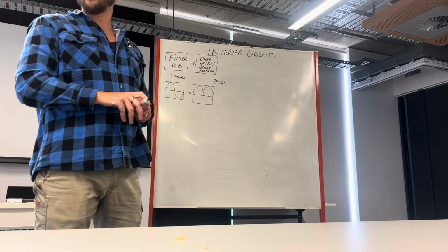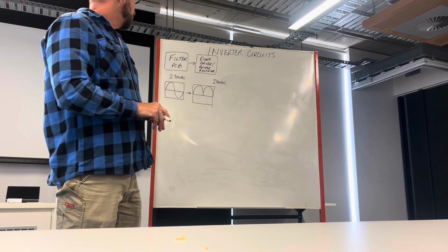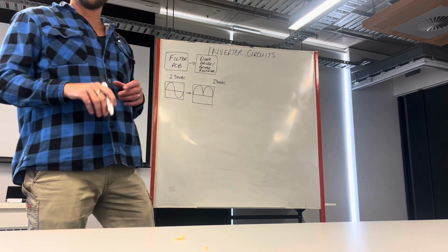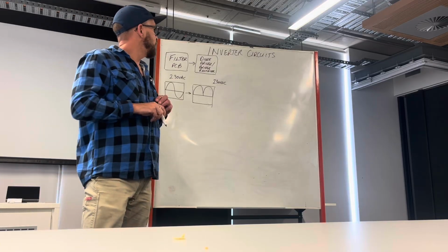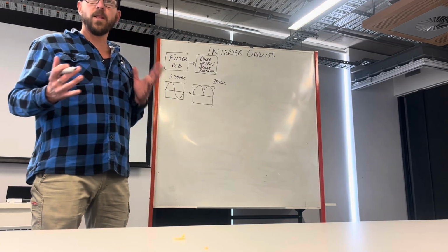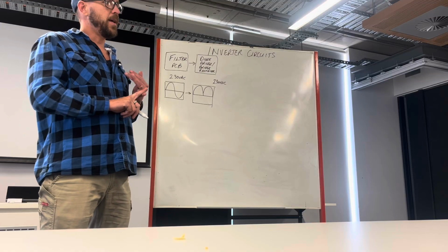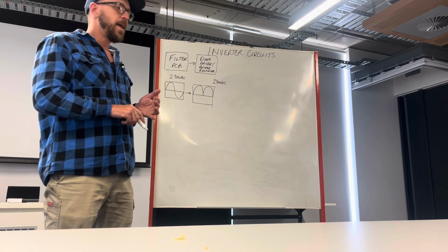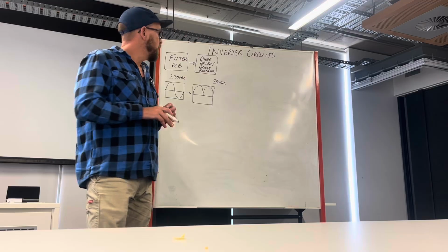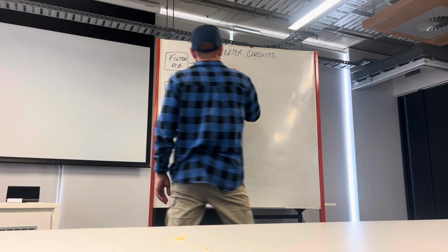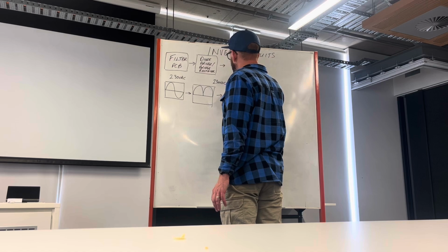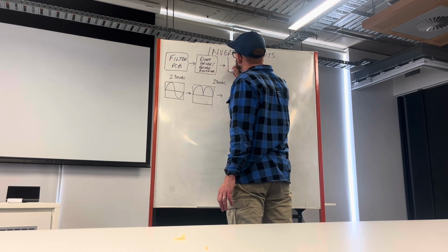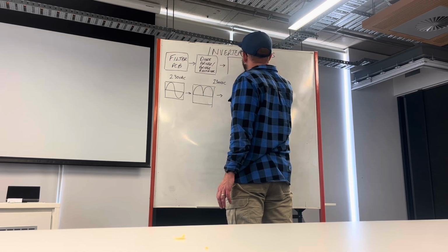After the bridge rectifier, we will normally go through some power factor correction equipment. The Fujitsu products that I'm more familiar with, that includes active filter module, the reactor. So I'm going to draw those here on the board. And this is where we're starting to see the voltage get smoothed out somewhat.